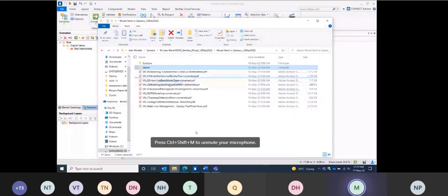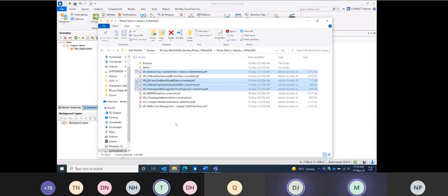Okay. So welcome back, everyone. Thanks for joining again. So yesterday we covered 4 workshops. Today we've got 3 workshops, but the 3 today are a bit more in-depth than some of the ones yesterday. So yesterday we started with the very simple importing of just the pipes and the junctions, and then we went and fixed it up by morphing some elements and then putting some settings into those elements, so a pump curve and some PRV settings and of course tank elevations, reservoir elevation.